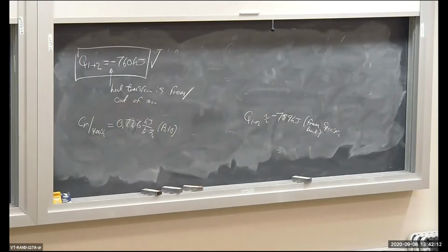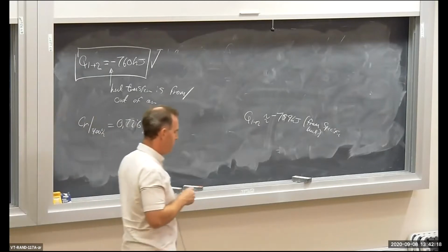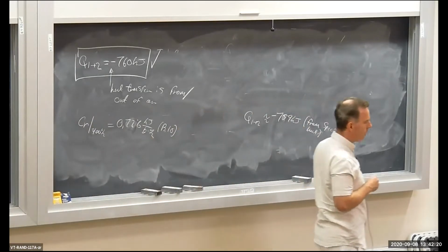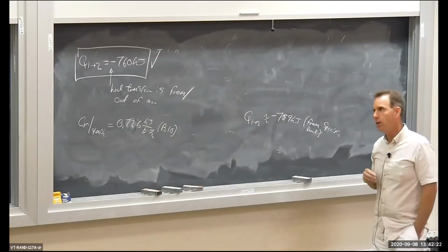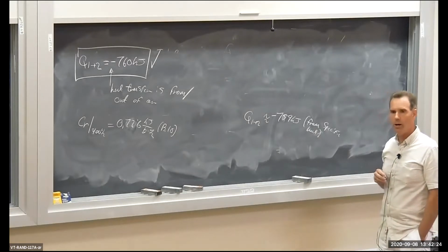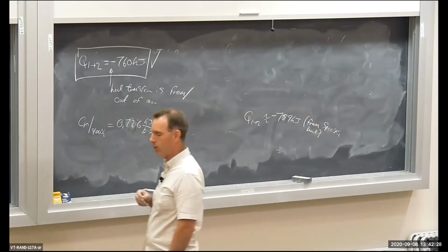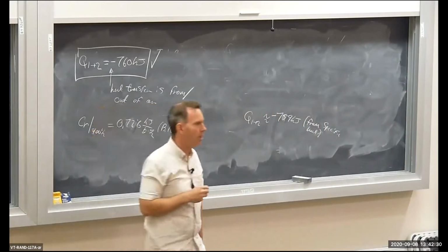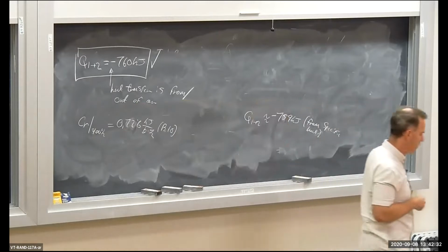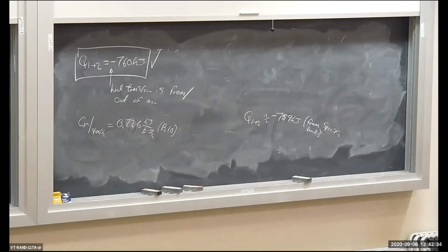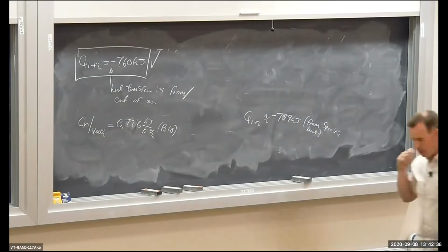If you want to go through and check that the ideal gas behavior is valid, I think you'll find that it is. The minimum temperature in the system is 300 degrees Kelvin. The critical temperature of air is what, 133 degrees Kelvin. So you're going to get a reduced temperature minimum greater than 2. And I think you'll find the pressure is what? What's the critical pressure for air?